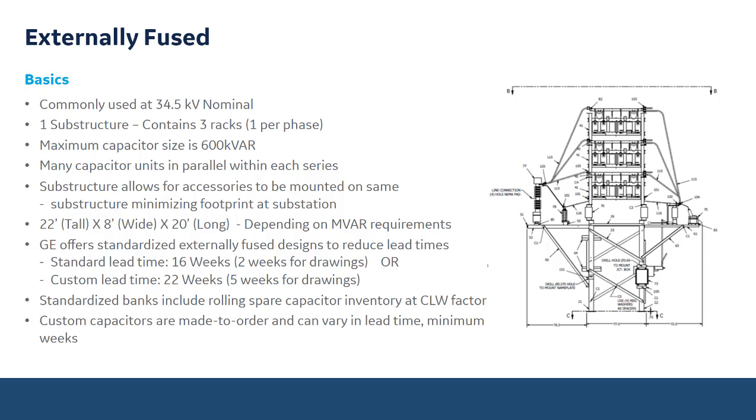The other advantage of using a standardized capacitor bank for its externally fused is the capacitors are a standard part number. So there's a rolling spare capacitor inventory at the Clearwater factory.